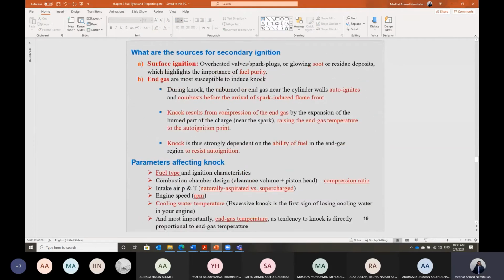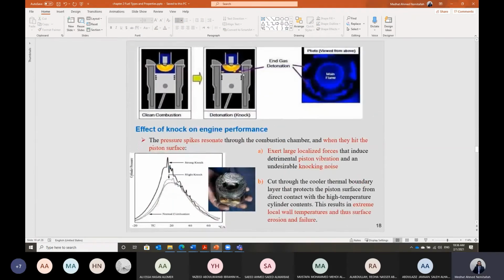Evaporative cooling means the cooling fluid in the cooling circuit undergoes a phase change process in order to keep isothermal wall conditions. So the cooling water, let's say at atmospheric pressure, should be boiling at 100 degrees C. The cooling water will come at 100 degrees C, so that it will absorb the heat and be converted from the liquid phase to the vapor phase.